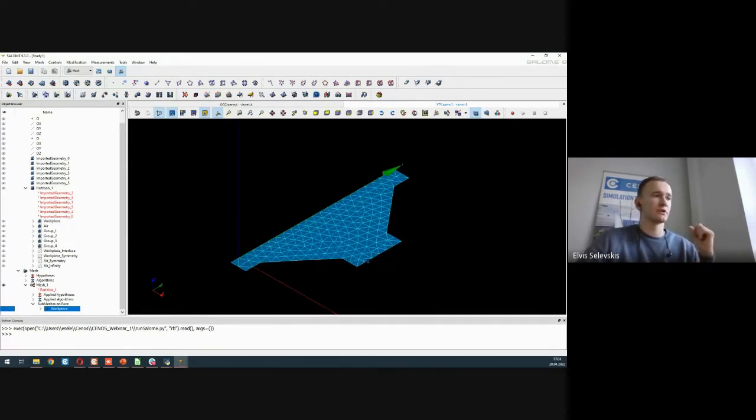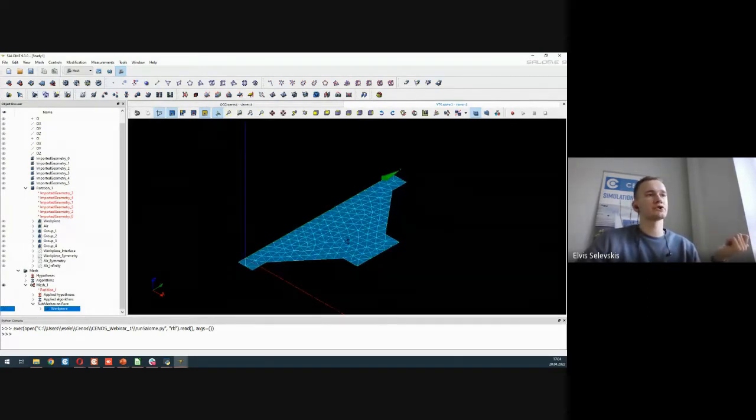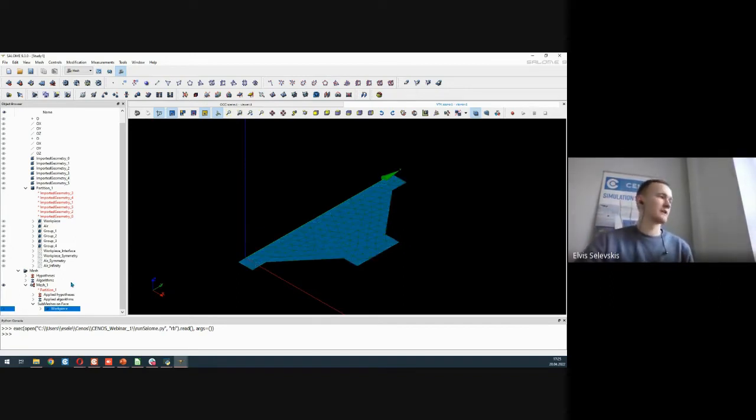but for a 2D case, I would for sure want to make it even finer because then again, the simulation will still be very quick. And if we want to see better heat distribution on the workpiece, then of course we need to have these triangles smaller. The temperature distribution in the end, like precise temperature distribution, will only be as good as your mesh is fine, pretty much. At least that's something to keep in mind.